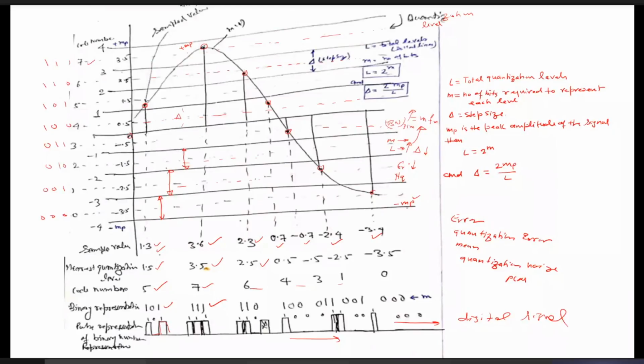And because of that, the signal to noise ratio, which it is preferable to have uniform and constant throughout the quantization process, will decrease, whereas we prefer to have a high value, uniform throughout. So that is not desirable. And these are certain drawbacks of the uniform quantization method.